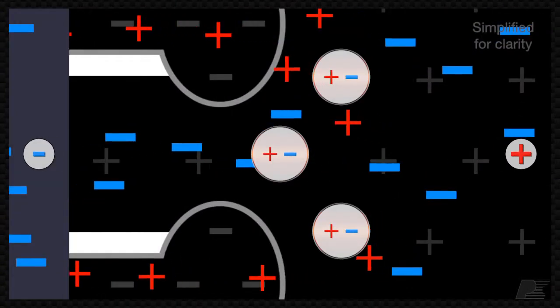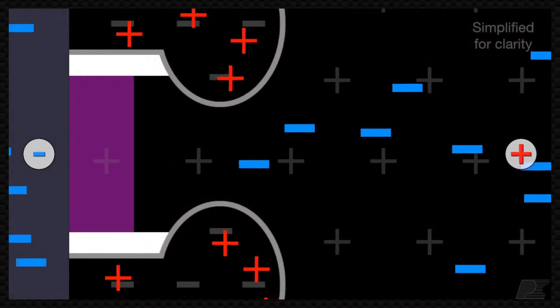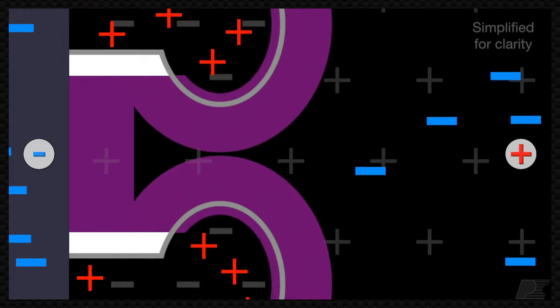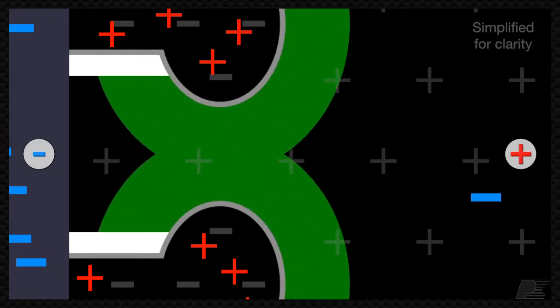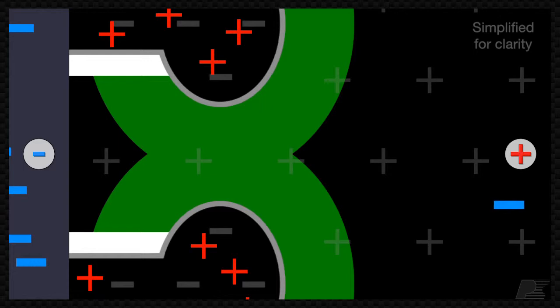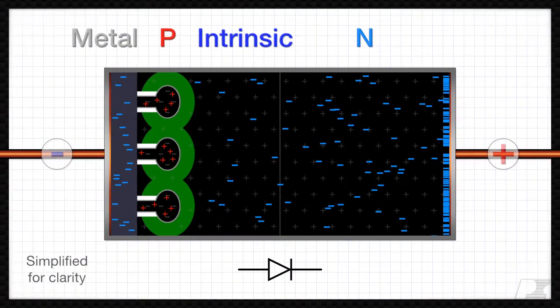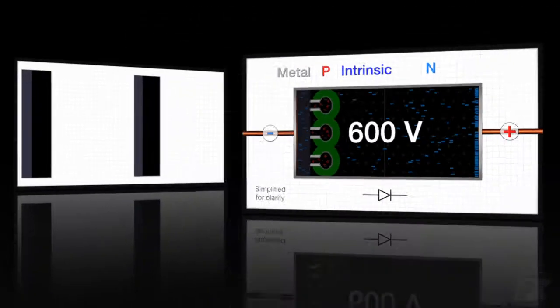When the diode is reverse biased, it enjoys both the fast reverse recovery of the Schottky sections and low minority carrier injection losses from the pin effect, providing an extremely fast, low-loss recovery. Once the recovery is complete, the P-wells create strong, overlapping electric fields that pinch off the Schottky channels, preventing leakage current through the Schottky junctions. This allows QSpeed diodes to withstand a reverse voltage of up to 600 volts, while standard silicon Schottkys usually break down at only 200 volts.